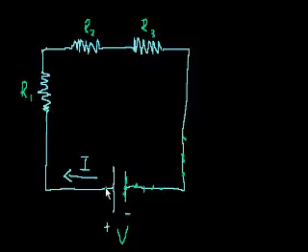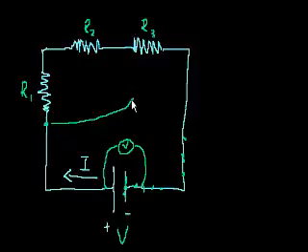So let's say I take a measure of the voltage across those two terminals using what we call a voltmeter, and I'll later do a whole video on how voltmeters work. But remember, when we measure voltage, we have to measure it at two points. Why is that? Because voltage is a potential difference. It's not some kind of absolute number. It's essentially how badly electrons want to get from here to here. So if we measured the voltage between those two points, it would be the exact same thing as if we measured the voltage between these two points, theoretically.